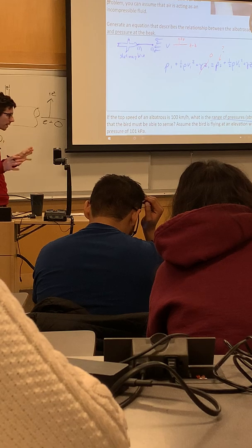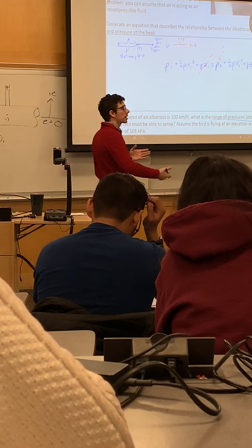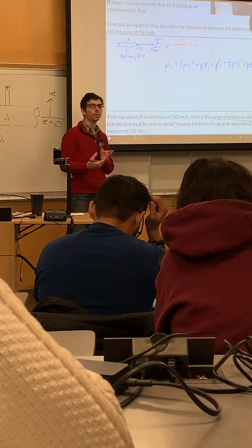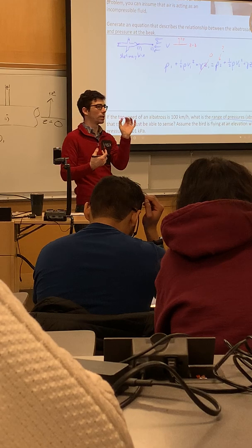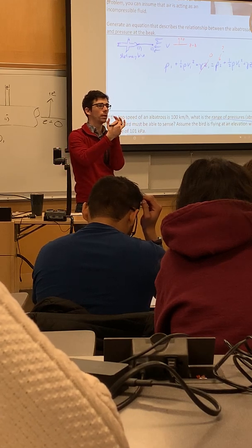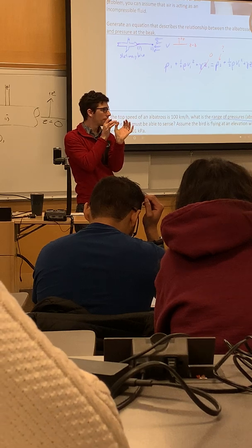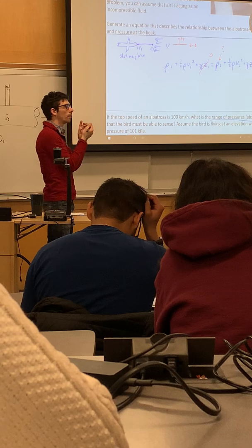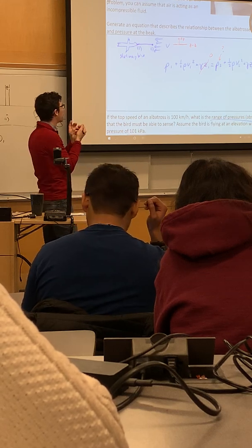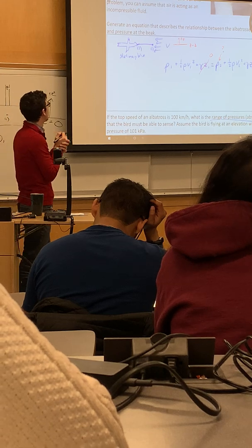Right? If you identify that this is a stagnation tube, then you can look at the definition of the stagnation tube, or you can think through what's happening in this scenario: we have essentially an opening to the fluid, and downstream of that opening, we can assume the fluid is static, right? It's entered a chamber where the fluid is not flowing anymore. So that's the definition of a stagnation tube.